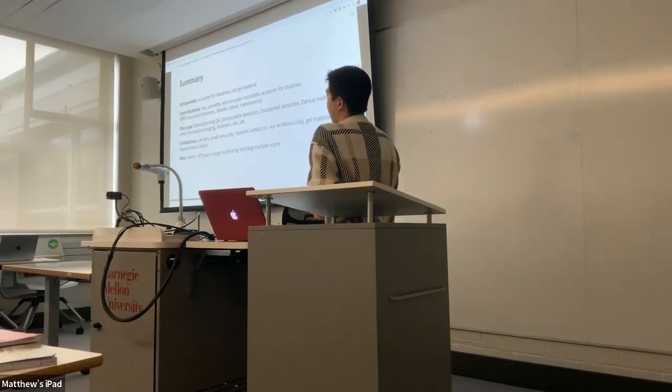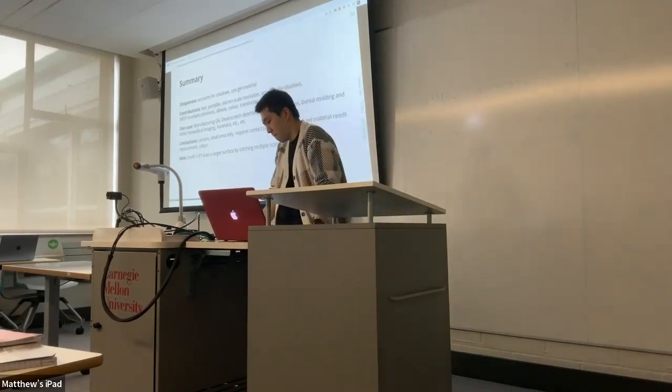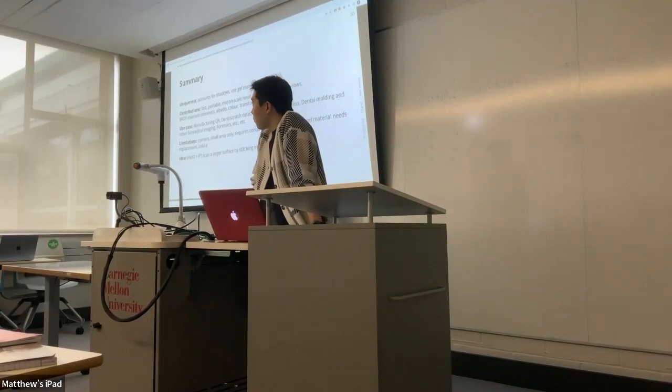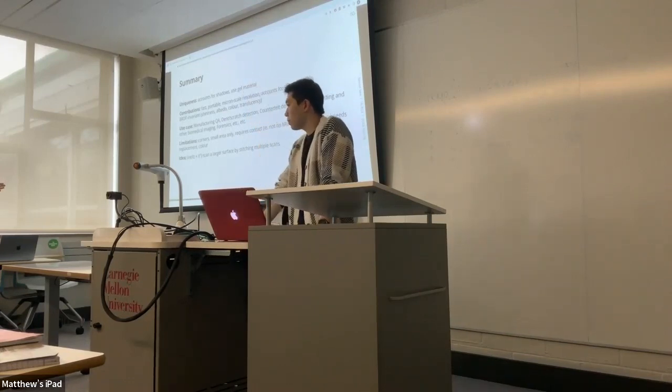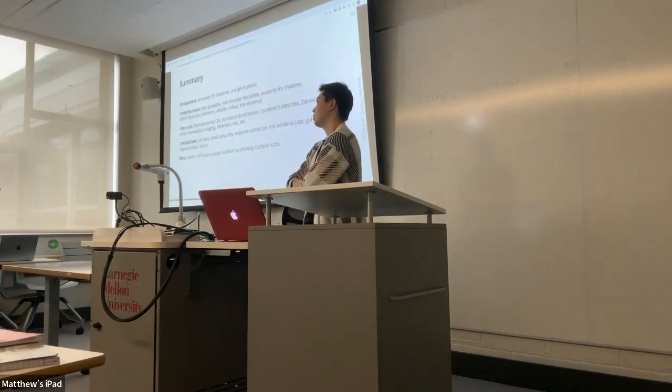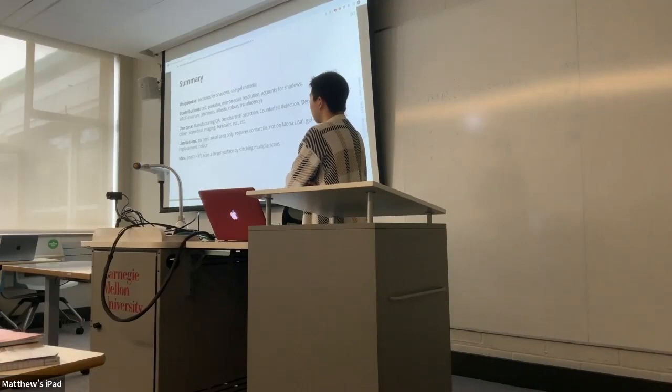Another potential way, and I don't know what this is actually, but maybe you can use the fact that the camera is typically focused on this GelSight pad, assumed to be in a position. As you go further away from that position, things can get defocused. So what if you use these grid dots and measure their defocus to figure out not just normal orientation, not just shearing, but maybe displacement as well, getting a better sense of depth?